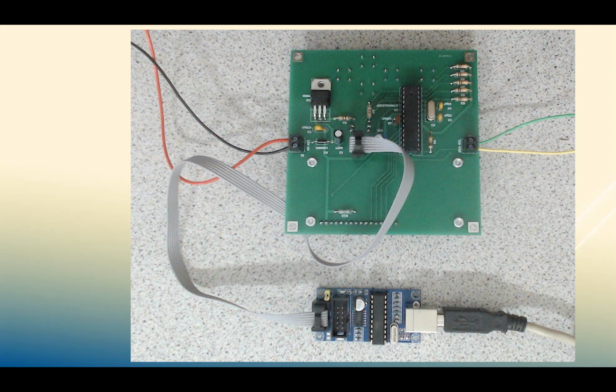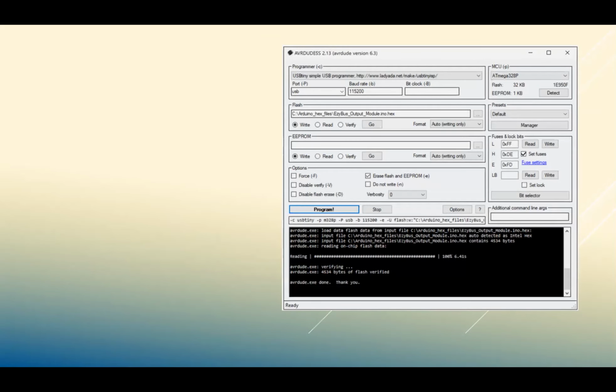It's a bit more complicated because you've got to do things like this. For those of you who are used to programming with PICs, you'll know that in the pragmas and so on, you can say, make it run at a certain speed. You can set a bunch of parameters that should work in your code. But when you're programming this way, you have to use what they call fuses, which then set the speed and other factors.